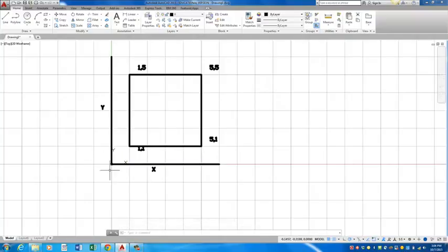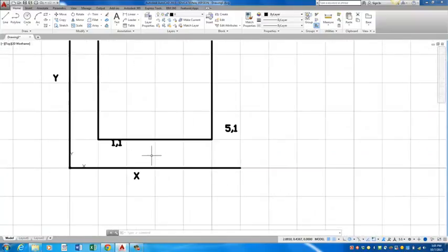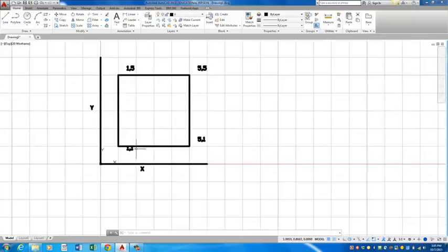Okay, so now that was using the absolute coordinate system. Remember, the biggest thing you have to remember about absolute coordinates is all of your moves are based off of a 0 point. So 0, comma 0. And then you just use the grid spacing to determine where these points are. Now, relative coordinates are a little different animal. Relative coordinates are based off your current position. It's kind of the best way to explain it. Relative coordinates are based off your current position.